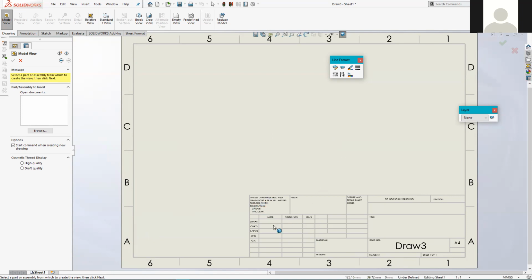And all the text that you get about dimensions are in millimeters in that standard, and all the sorts of things that you'd expect on an engineering drawing. But what we need to do first is tell this drawing what part file we want to make a drawing of. Given that we've not got a part already loaded up in the background, we need to point it at our folder that we just saved our part into.